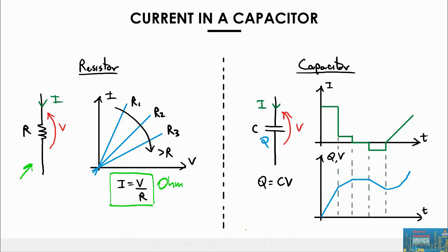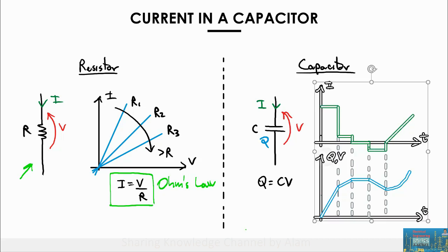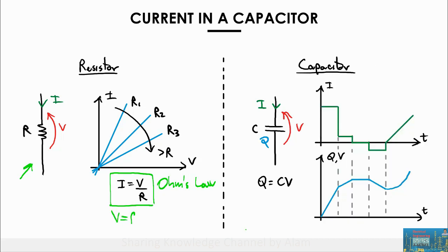This is called Ohm's law, and is a representation of a very simple relationship. It's a linear relationship where the current through the resistor is simply equal to the voltage divided by the resistance. And you can also obviously write this equation in many different ways. For example, you can write it like this: V equal to resistance multiplied by the current, and vice versa.